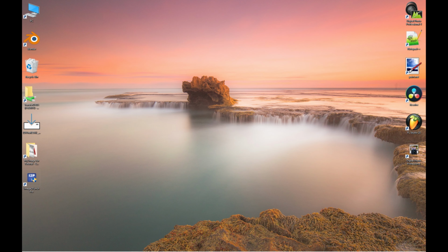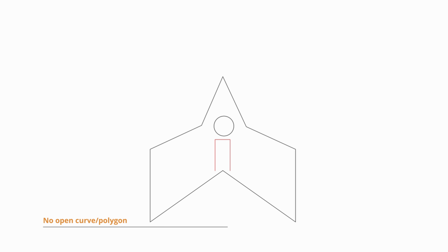However, there are a few restrictions and limitations when creating a shape for a custom tool. The first one is that the user needs to make sure there are no open curves. All the open curves will be ignored when importing a custom tool shape from DXF.